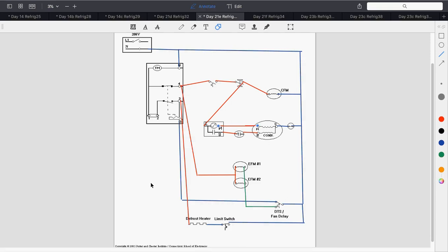Now I have one more wire I have to toss in or nothing's going to work. What is it? Your line voltage. Yeah, let's get this line down to 1 and 2. That's a brass band. You see that little band connecting them? That's a copper band, so it really doesn't matter where you go on that. Right, so you're connecting it right there in the middle.